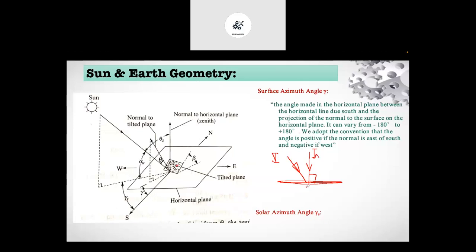So that is the characteristic of radiation and the transfer of energy. So the intensity of the inclined ray and the intensity of the normal ray are going to be different. The normal ray will have maximum intensity, whereas the inclined ray will have less intensity than the normal ray. So how can we relate these two intensities? For that we use the cosine law, which means the intensity of the inclined radiation is equal to the maximum intensity into cos of theta.